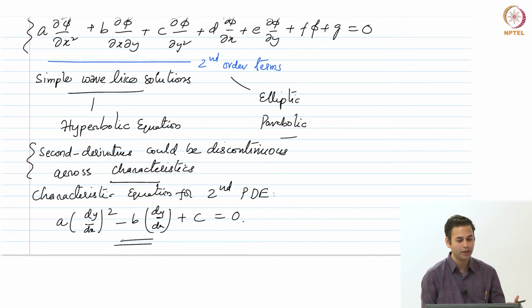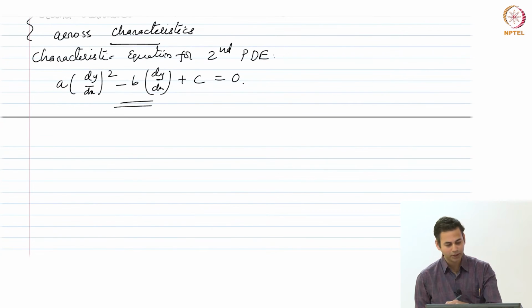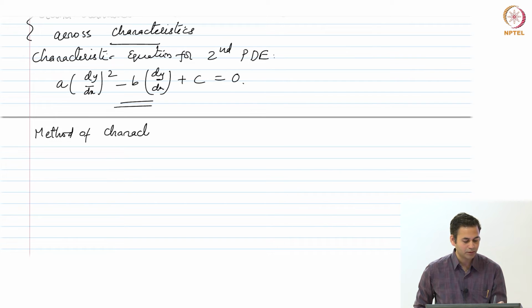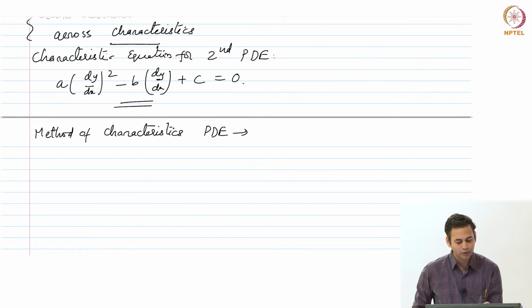But we are not discussing that as part of this CFD course. If you have taken some course in gas dynamics, you would be taught some of these characteristics and reducing the equations along the characteristics and solving for them. This is known as the method of characteristics, which you can look up, and which reduces the PDE to ODEs along these characteristics.